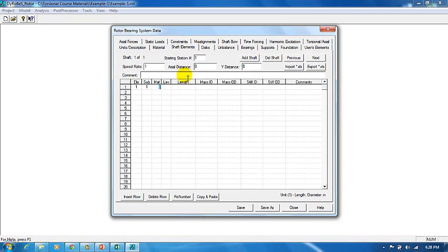as well. Now what the sub is, for very long rotors, for very big models, it's very useful to use sub-elements because it helps with reducing the computation time. In our particular case, since we're building one element, it doesn't matter, so you just keep one sub-element. Now, under material, type material 1, and I'll explain why you type material 1 in a second.